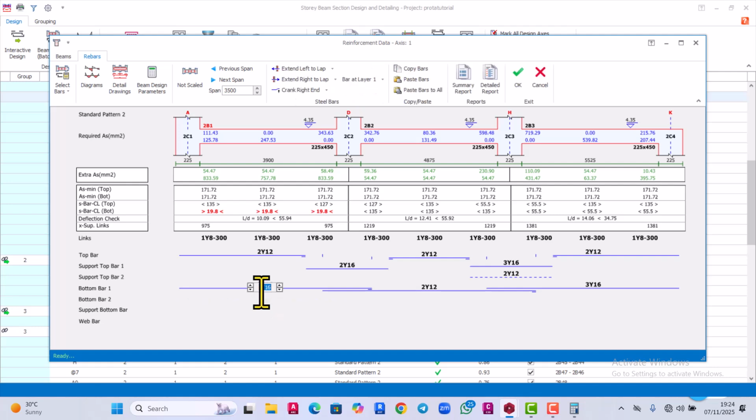So if you increase this one, it will start showing red. Understand? Even if you observe that this is less than 37, it's showing red. This is based on the settings we made. Let me reduce it. Based on the default setting, the minimum spacing between two reinforcements is 50 mm. That is the software default, and that is why the 61 point something is not showing red. But once you are less than 50, it will show red.